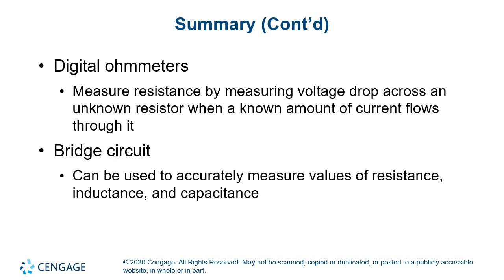The last of the measuring tools we discussed was a bridge circuit. And of course, bridge circuits are designed to amplify small changes in things like resistance, inductance, and capacitance. And by the way the resistors are configured, for example, in a Wheatstone bridge, we can determine the changes of a small variation in resistance and get a very accurate value for these. So the bridge circuits allow us to do that.